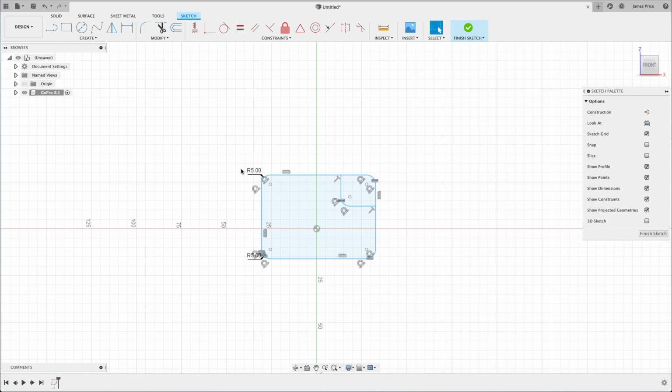Now, we have two remaining fillets for the camera profile, although if I repeat the fillet command, you will notice that some of the automatically applied constraints are now lost. Fusion cannot establish how to repair these, as we have created a feature that has multiple points we could connect to. In this case, open up the line command again and repair these gaps using the automatic snapping. Once finished, you should see the two profiles as indicated by the light blue shading.